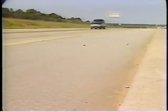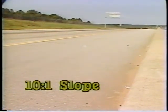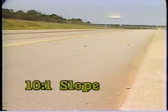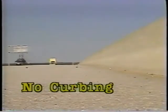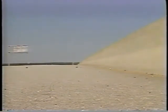When selecting and installing a barrier, it's very important that it be placed on relatively level ground. The cross slope of the area in front of the barrier should not be steeper than 10-to-1, and curbing must not be installed in front of the barrier. Either of these conditions could cause a vehicle to vault over the barrier instead of striking it at the proper height.